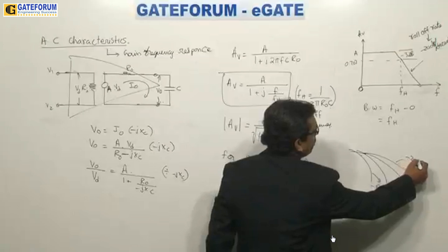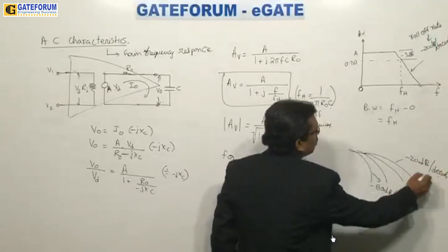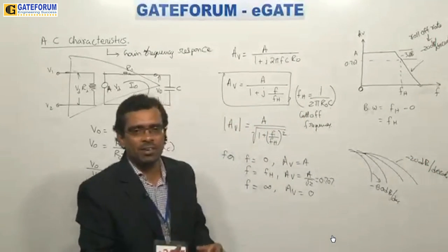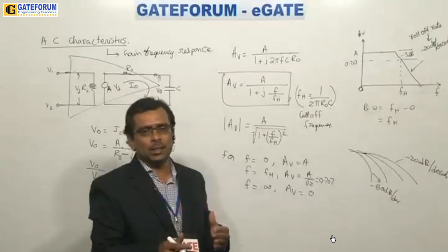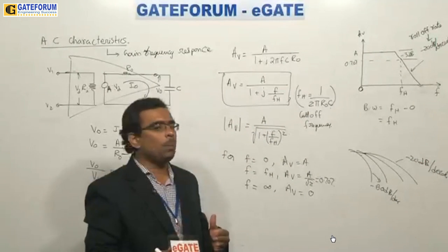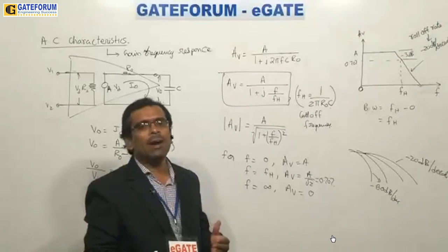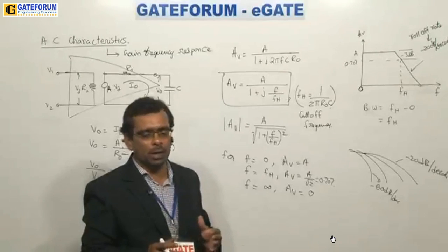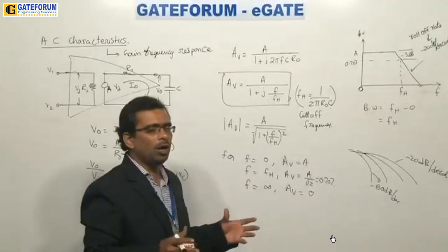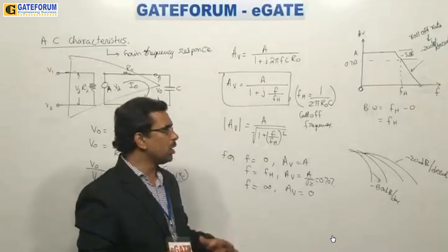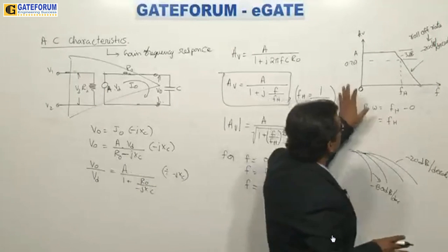20 dB per decade. So like this, the fall of gain is called roll-off rate, and the more roll-off rate you have, you will try to get an ideal condition. But there are additional problems with that. Why? Because bandwidth will be changed. Bandwidth will not become constant, because gain bandwidth product is always constant. That is the reason you will not get both at a time. What is gain bandwidth product? We'll see. For the time being, try to remember this point.